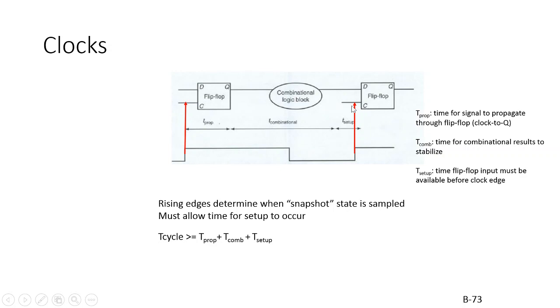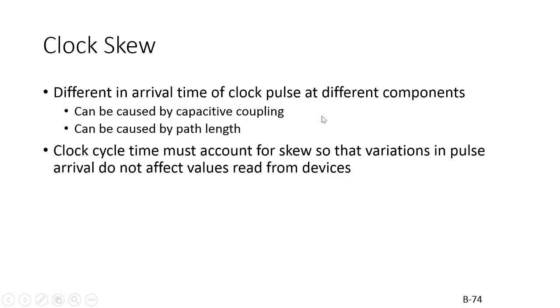This is a drastic example I just spoke of, that would be a lot of wiring, but just hypothetically, then you get skew. Even though the clock is consistent, and let's say it's a synchronous system, so it depends on the clock, when that edge arrives, either rising, as in this case for both of these, or falling, is going to be at different times because you have different lengths of wires. Well, that's kind of a bummer. So that's called clock skew.